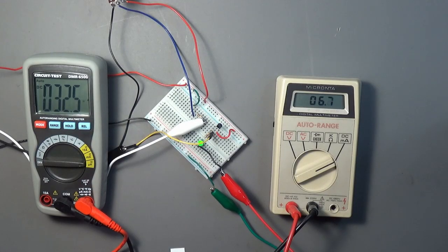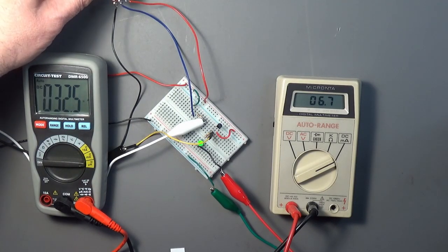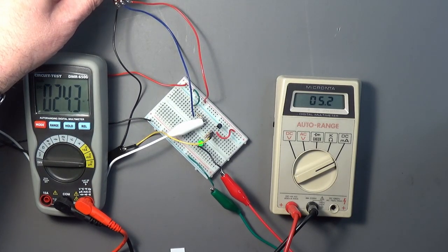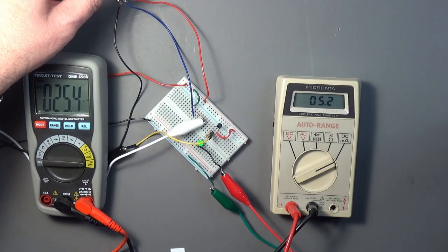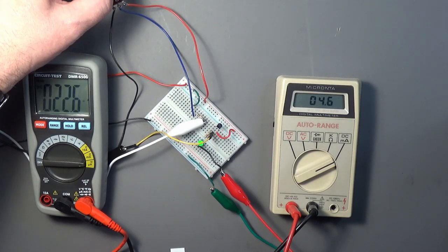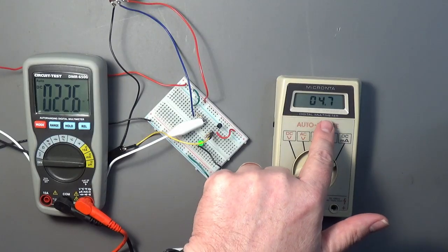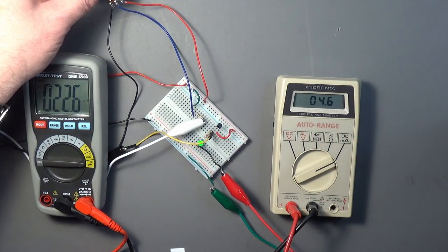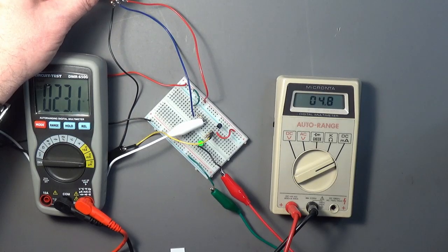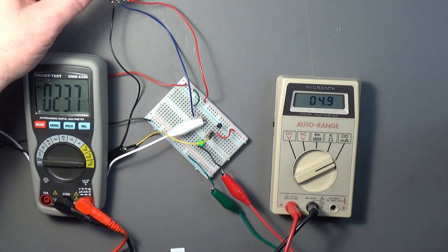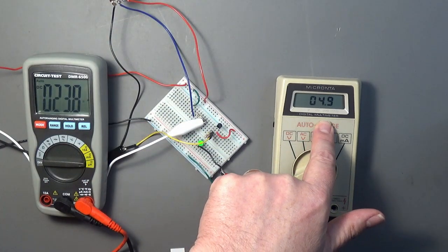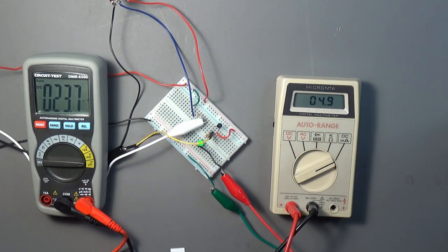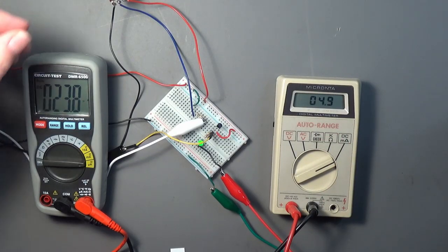And that's the other function of a transistor, amplifying. It's taking this small signal, and very, very small changes in this signal cause a very, very large change over here. So we've got 4.7 milliamps and 2.26. If we put this up to 2.36, like so, we're now up to 4.9. So an increase of 1 microamp has caused a large increase there.